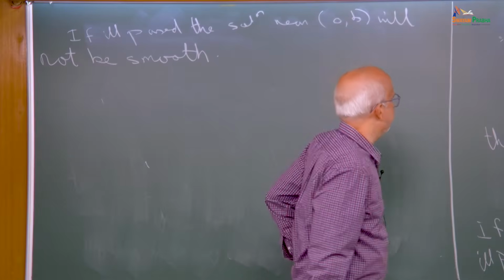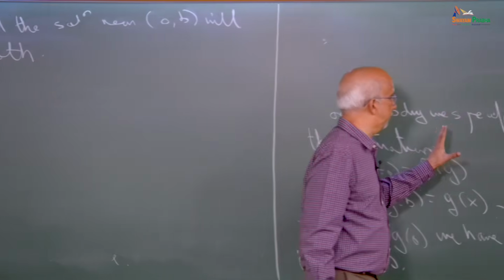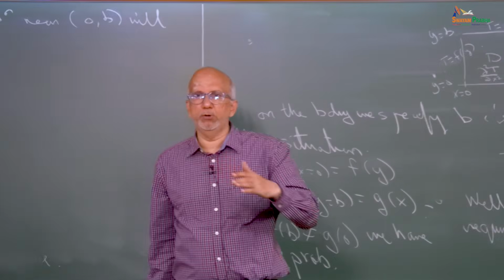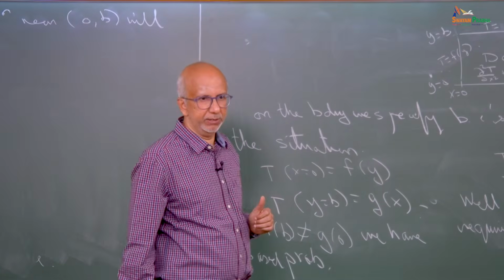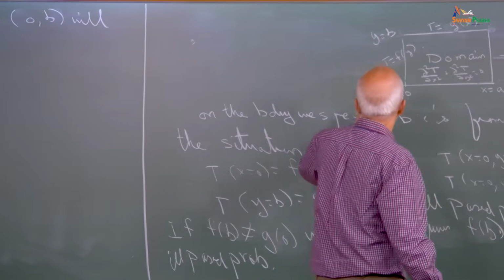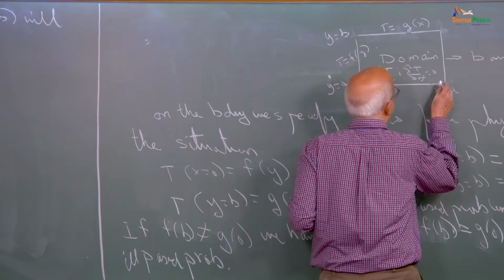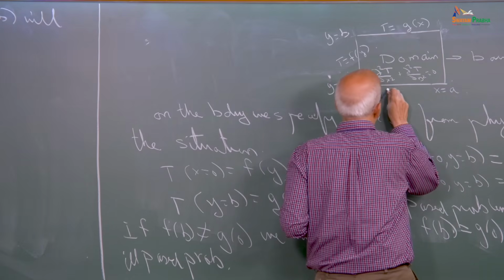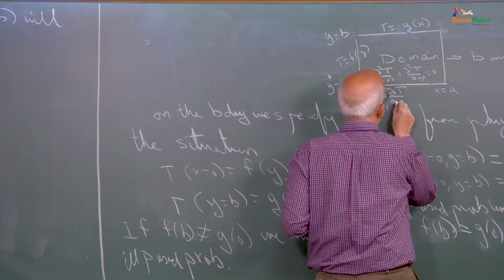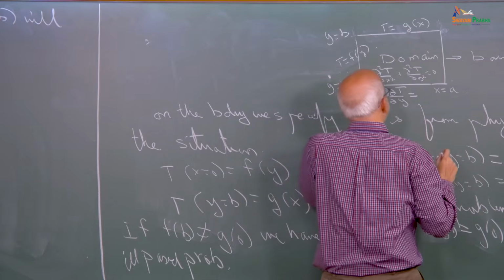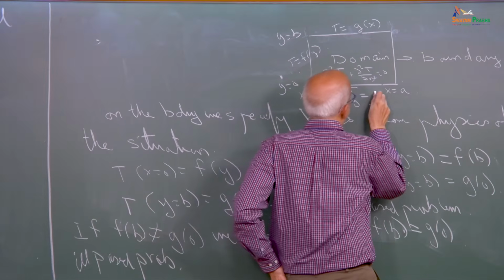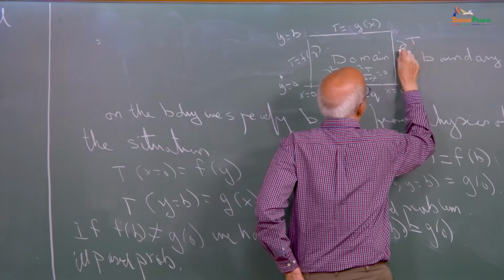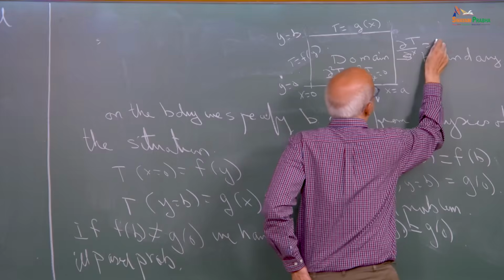Now, I need to specify, so whenever you are talking about solving a differential equation, you need to specify things on the boundary, because this is easy for you to see. Here, for example, temperature is f of x and maybe I am going to heat this guy here. So, dt by dy equal to q, and let us say I will put dt by dx equal to 0.